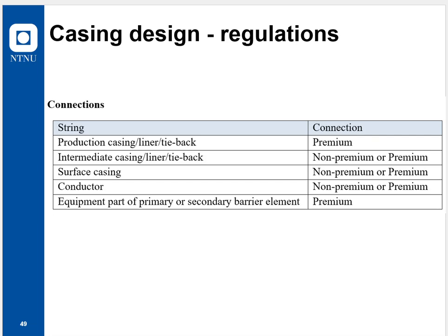Theoretical situation, but what you need to understand and what you should have in the back of your head is, can I bleed off the annulus, read off and bleed off, or is this a closed environment, a closed annulus? This is a very special case that you really need to consider. A well construction like that is a high risk.